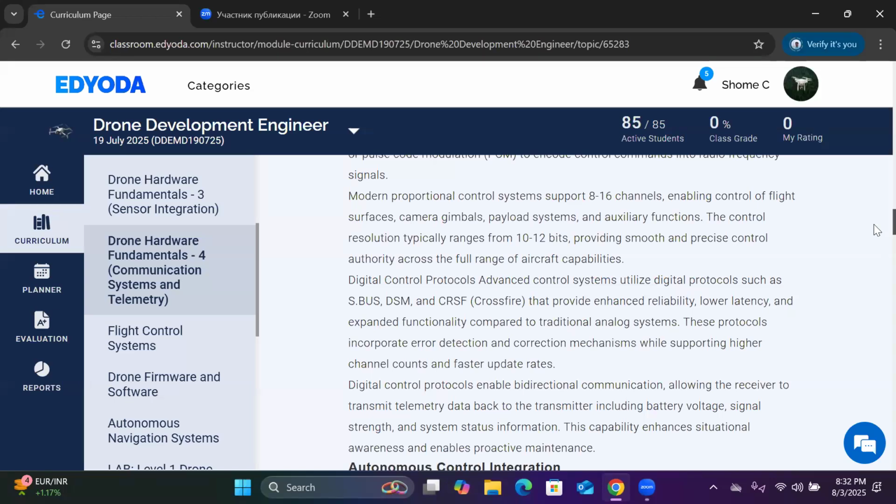Now suppose you are getting the data from the battery management system as well. Suppose this is the state of health or the state of the voltage, current or temperature for a particular battery system used in the drone. Now if the battery voltage is below a critical value, the drone is blind, it is going on flying. The communication box needs to trigger an alert message or alert data back to the drone to say your battery voltage is low. You cannot carry on the flight to the fullest extent. So you abort the mission and come back to the home location.